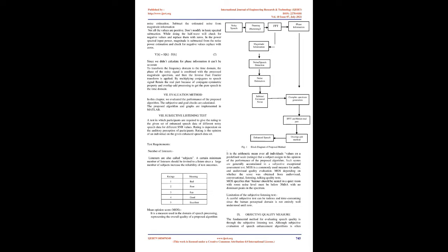3. Method. This approach operates in the frequency domain and makes the assumption that the spectrum of the input signal can be expressed as the sum of the speech spectrum, Sk, and the noise spectrum, Dk. Xk equals Sk plus Dk, (1).